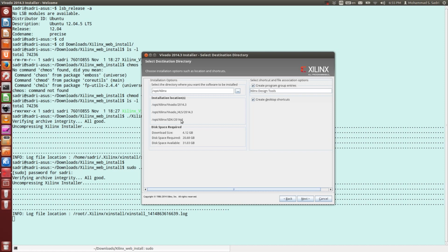And it has happened sometimes that, for example, you are using a piece of IP and Xilinx upgrades in fact Vivado tool, and exactly that piece of IP in the next version of the tool has a kind of problem. For example, there was this PCI Express AXI bridge.